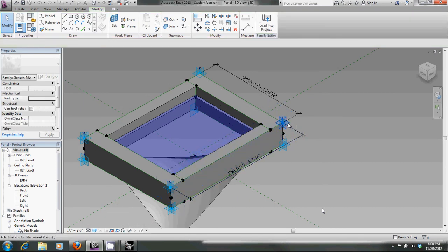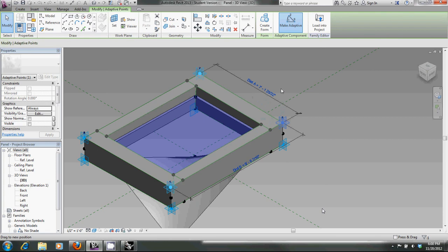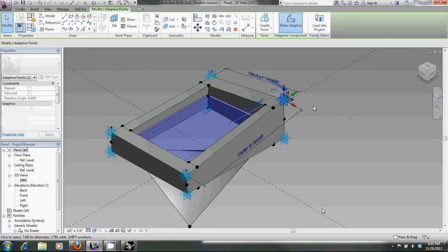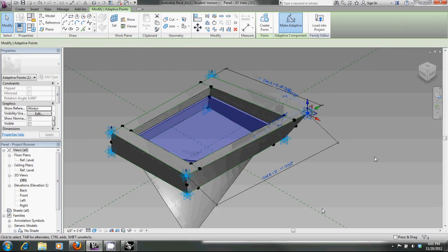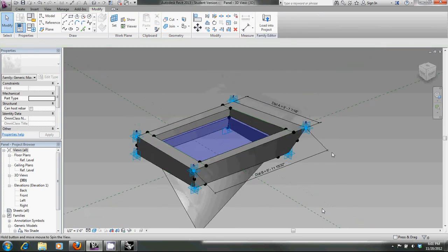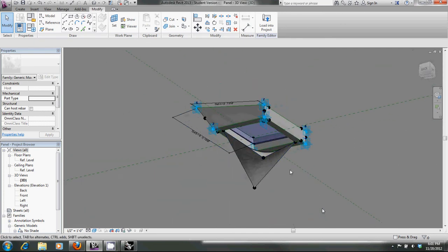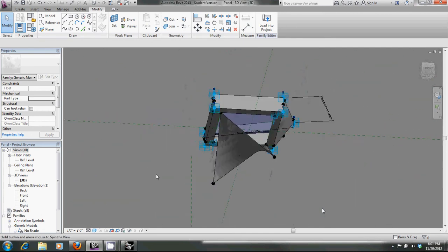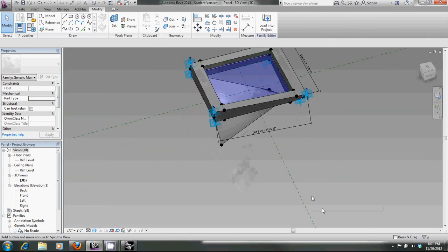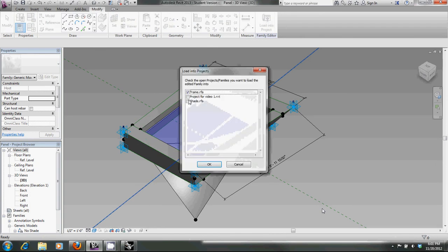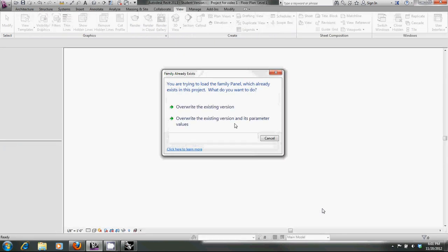This one's got this same type of setup, all the different points, all the different adaptive points, only this one has a glass inset into it with a sort of shading device hanging off of it, and you can see we can flex this around, and the panel then changes shape and form so that wherever those points are as they come in from Rhino, this panel can just adhere to it and basically just snap into place and create the form. So that's the beauty, I think, with this workflow is, we can build any type of panel we want here, load it into our project.